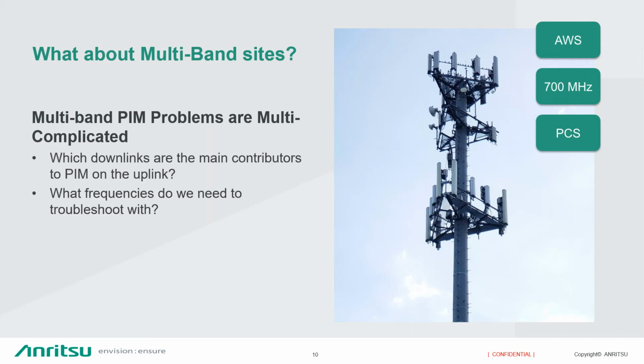So it's very important to understand that in diagnosing PIM for a multiband site, you have to understand which downlinks or transmitters are the main contributors, and which frequencies we need to troubleshoot with.